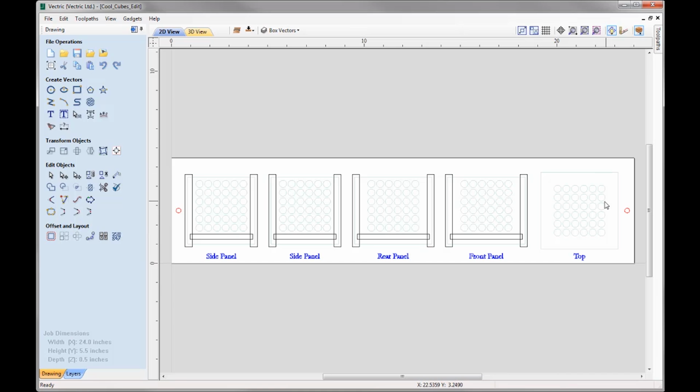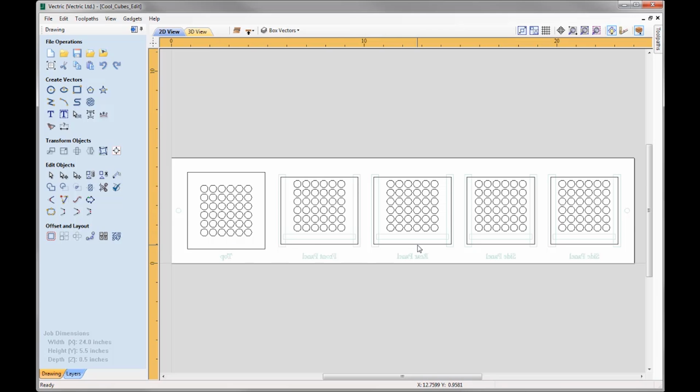where we'll then take our material off as we've finished with the top side, and then we're going to put the dowels into the spoil board, and then when we flip our material over, we're going to align it back in X and Y into the position, secure the part in place, where we'll then go and run the toolpaths for the bottom side. I'll look at machining all of the decorative elements, followed by profile cutouts to cut all of these panels out. So let's go and run these toolpaths.